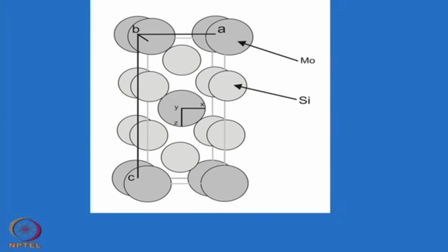Many of the furnaces, the basic principle of heating a furnace is basically Joule heating. That means you pass some current through these materials and there is I square R heating. Okay. So, current square into resistance. So, these ceramic materials, because they have a high melting point and also have a fairly low resistance, you can pass fairly large current through this, and as a result they will heat up. So, these are the heating elements of different furnaces.